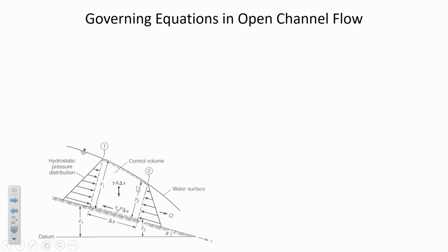The depth is getting less. Do you notice how it's deeper upstream and downstream the depth of the water is less? That might be that this water is approaching some sort of a fall. And a waterfall draws down the water in the direction of flow. So there's a curve in this water surface profile. So it's deeper upstream, it's shallower downstream, and so that means here at segment 2, there's not going to be as much pressure because it's not as deep. So those are the first two forces that we could look at.